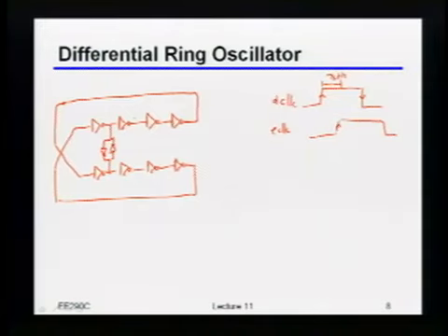Again, just to make sure everybody is clear as to how this thing works, if I called that one right there 0 degrees, actually, sorry, let me shift it back by 1. If I called this here 0 degrees, then this is 180 degrees, right? And now each inverter delay gives you 180 plus a 45-degree phase shift.